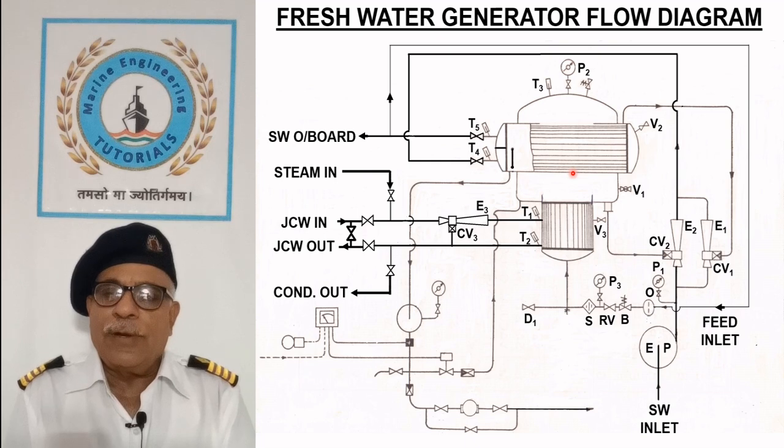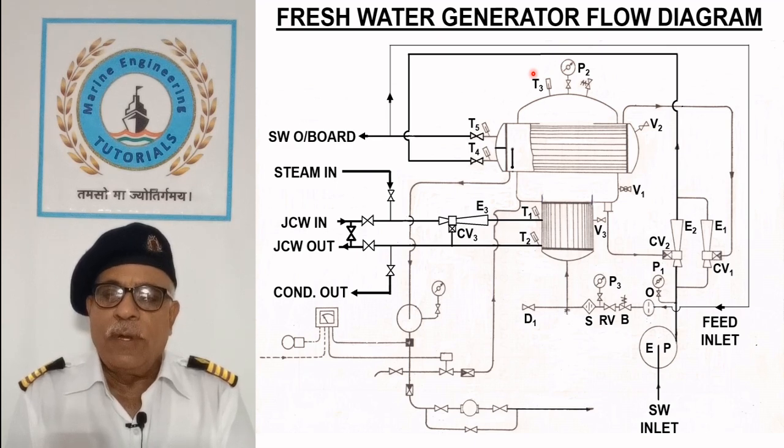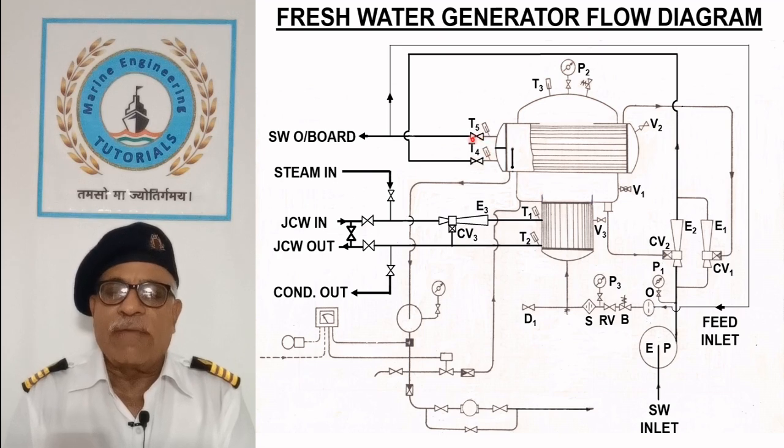The shell temperature is recorded from the thermometer T3, which is dependent on seawater or the condensation temperature. Performance of the condenser is observed by monitoring the inlet and outlet temperatures from the thermometers T4 and T5.